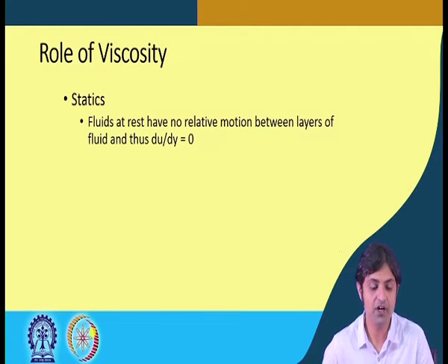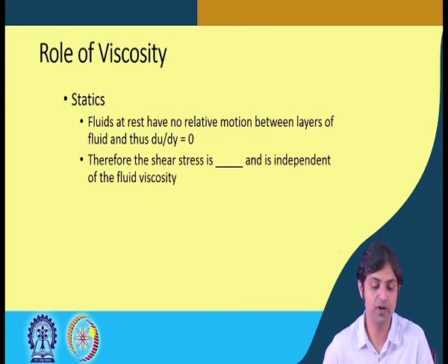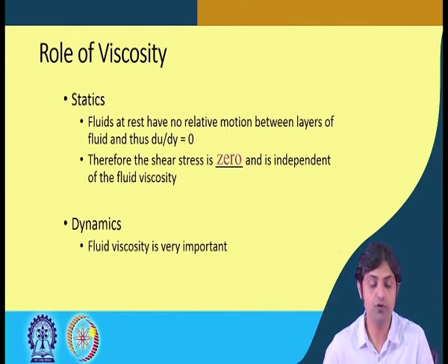It is important to note that fluid at rest has no relative motion between layers of the fluid, right. Statics means rest. So when the liquids do not move, there will be no velocity difference between those two fluids, so du by dy is 0. Therefore the shear stress is 0 in case of fluid statics and is independent of the fluid viscosity. In case of dynamics, fluid viscosity is very important because the water moves, different layers will have different velocity, and thus there will be a velocity gradient du by dy.